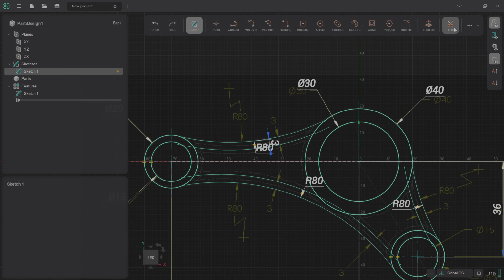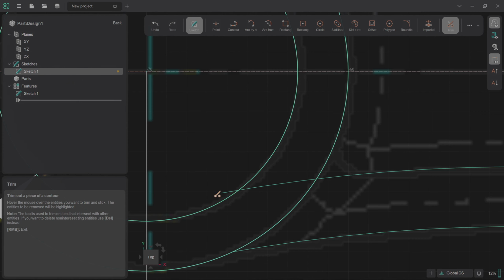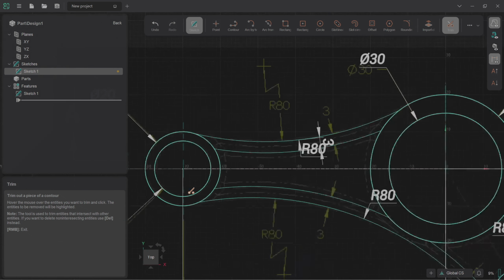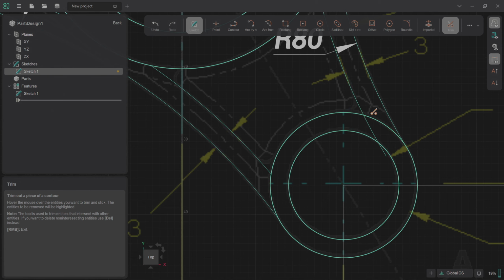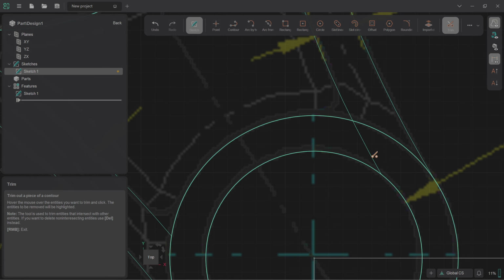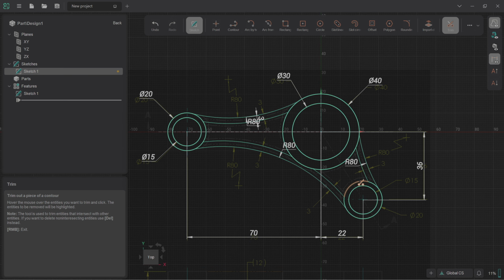So let's go to the trim tool, and I'm going to break this line here, and we're going to take off all of the excess points along these, just because when CAD is left to try and work out what's relevant and what's not by itself, and this isn't a reflection on ENCY CAD specifically, it's just I've been working with various CAD programs long enough to know that if you can stop it from having to make decisions itself, it's generally safer to do so.